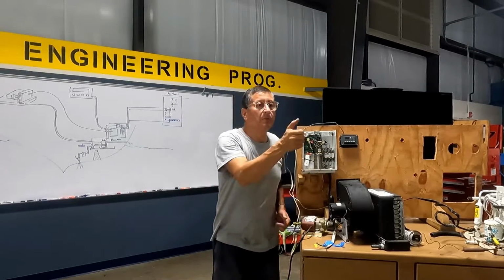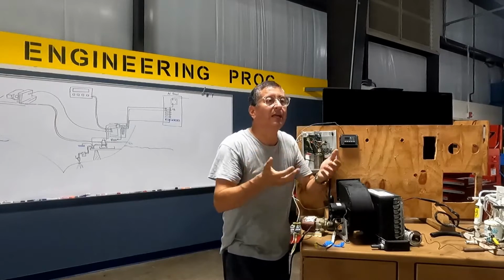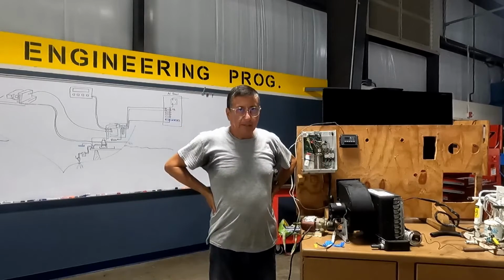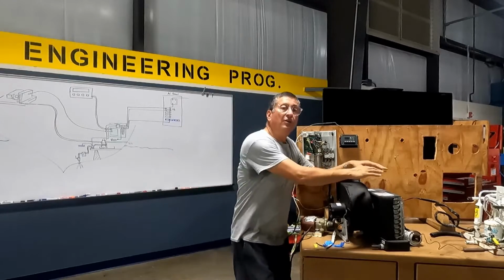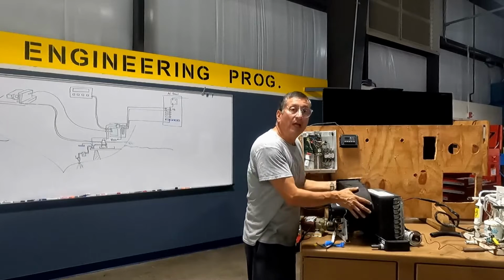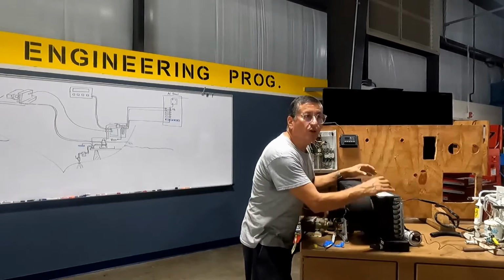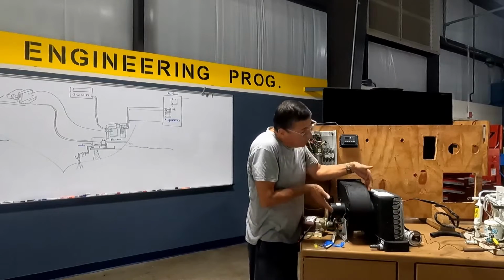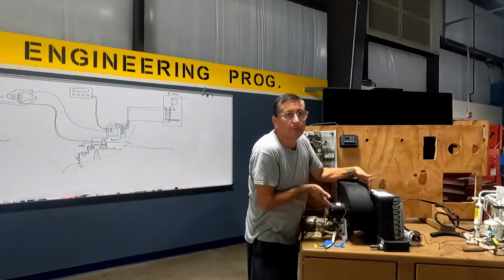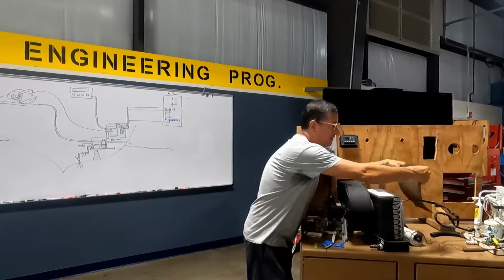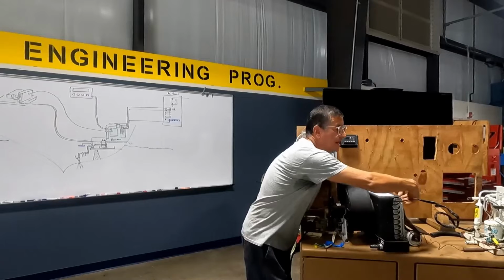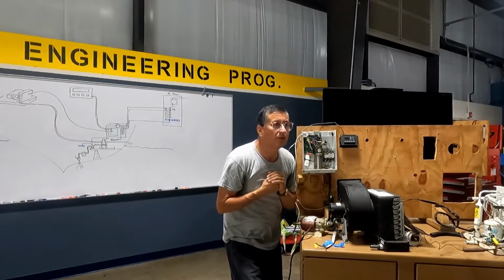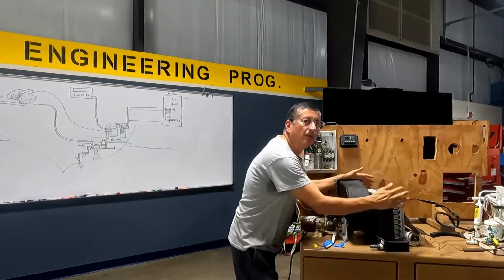The thermostat is the element that sends the signal to activate the complete system, the whole system together. Ready, my friend? Okay. The evaporator is composed of two elements: the evaporator coil or indoor coil, and the electric blower. The blower suctions the air here, that's the filter. The ambient air passes through the frozen pipes, and you receive cold air here. Yes or no, Roqueta? This is the evaporator.